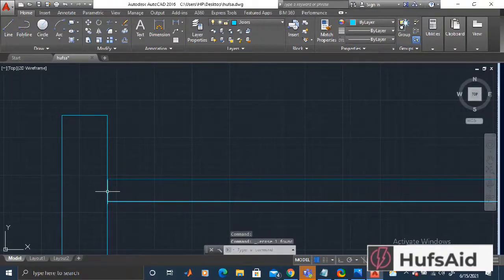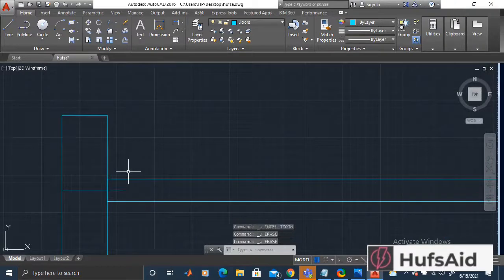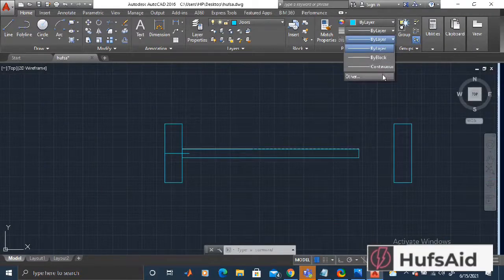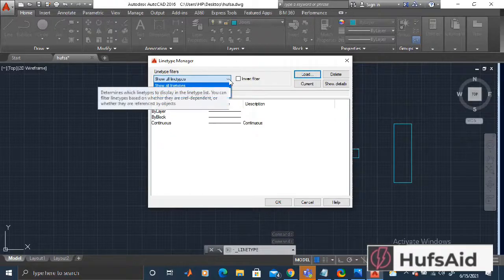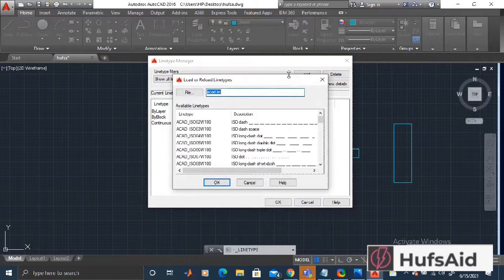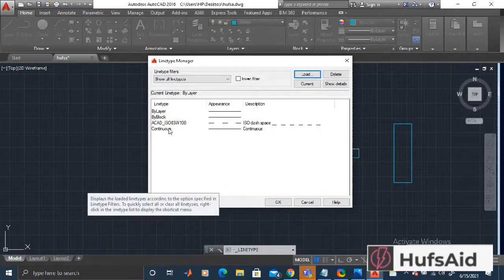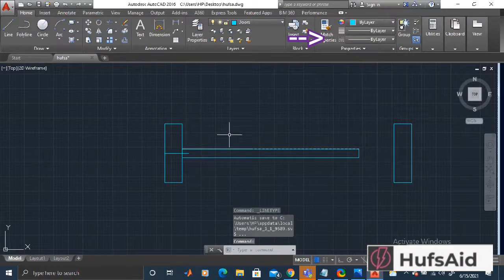Now this pocket door needs clearance in the wall, so we will have to specify the clearance area as well. So let's make another rectangle, and that rectangle would be made with dashed lines that would show that this portion would be inside the wall. That is the portion where you cannot conduit, and you cannot have any plumbing pipes as well in that area of the wall. So that's the drawback of pocket doors.